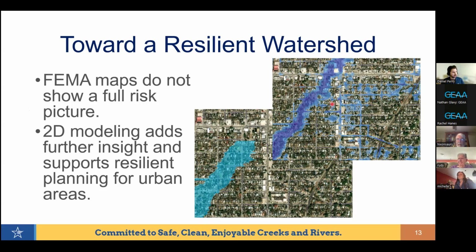So you see the flooding goes north of Hildebrand and some flooding comes from the east. So you can start using this information to input some of these green infrastructure or some of these detention ponds or other channels to make sure that you're slowing the water down or preventing it from getting to the channel that is causing the majority of the flooding.